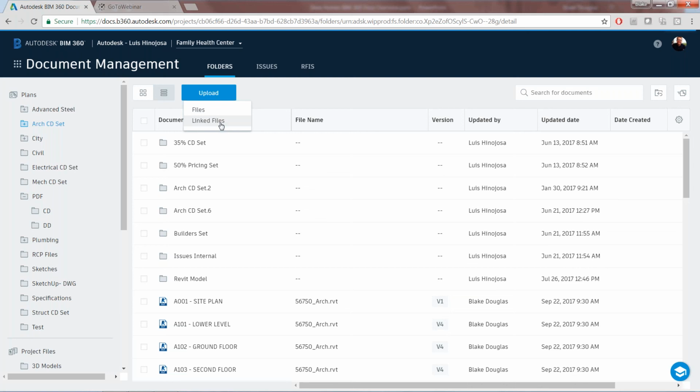It's not going to tie them into one another directly. So note that they simply need to be tied together within the design files. So if you're bringing, say, an AutoCAD file in as an XREF into a Revit file, you can do that in Revit, and then you would bring it in as a linked file.